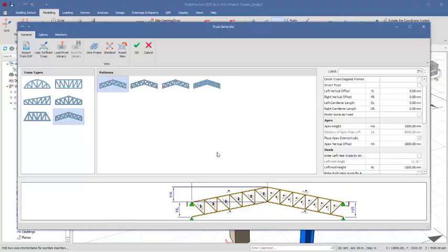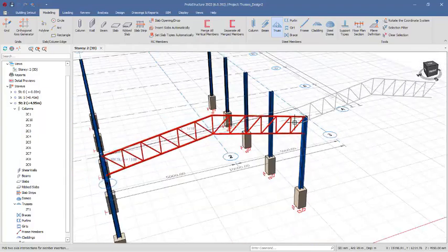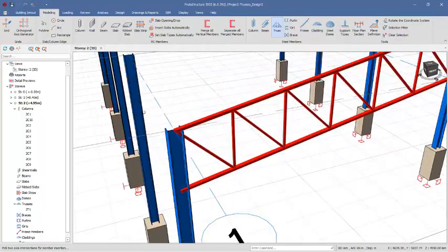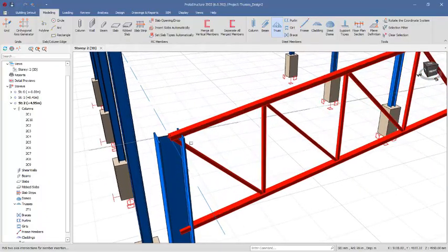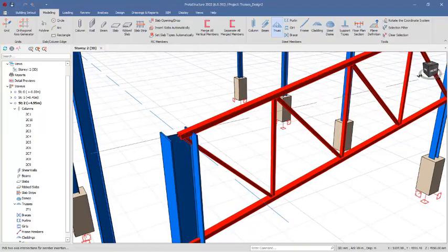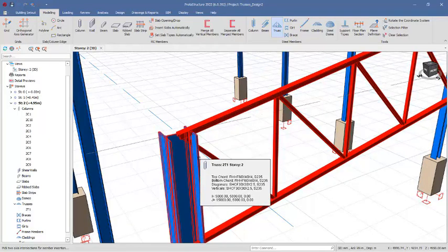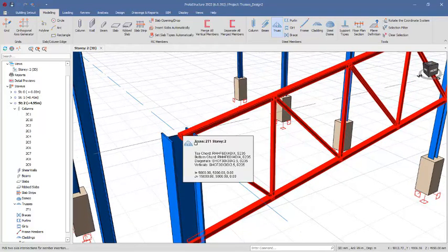Then I'll be explaining something to us. The OK option there is to have this truss placed. We are supposed to continue to place it, but for now let's get rid of that. So coming to this point now, what I wanted to explain here, if you check this truss right here, it is right on top of the stanchion, so we need to bring it down. Okay, we need to bring this point a little bit downward.